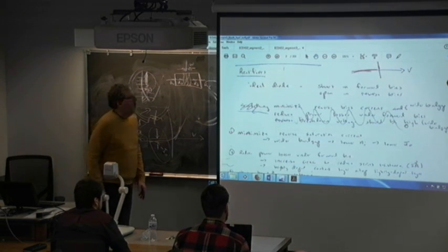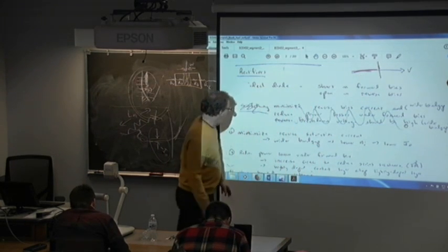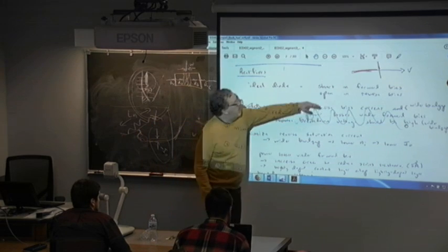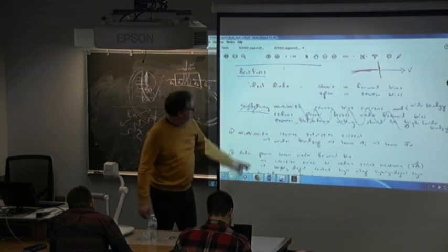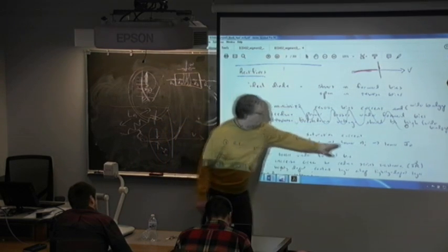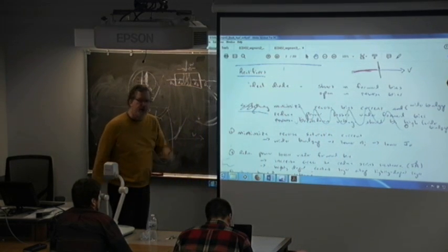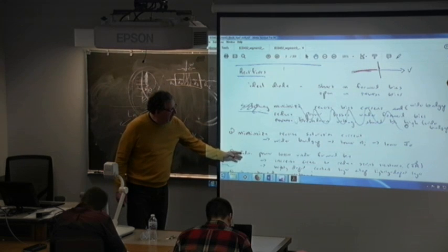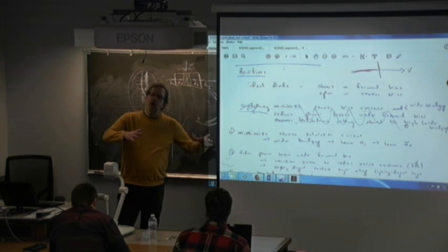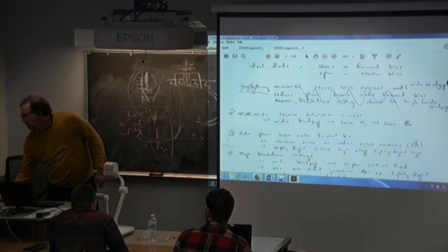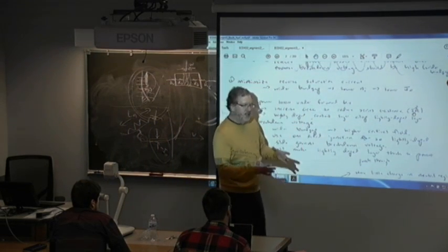So an ideal diode, I want to have a short in the forward and open in the reverse. So therefore, I want this to be completely open. To reduce the reverse leakage current, I might use a wide band gap, which lowers the intrinsic carrier concentration, which lowers the opportunity for generation to happen. Reduce power losses, where it rolls over the ohmic losses. I want to make the device very large. That reduces the I squared R joule heating by reducing the resistance, right?